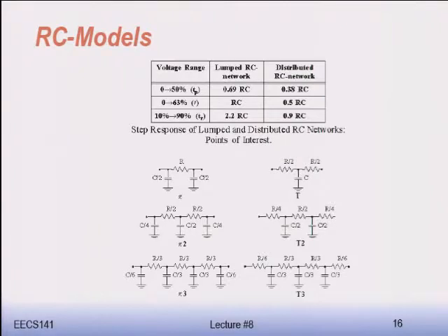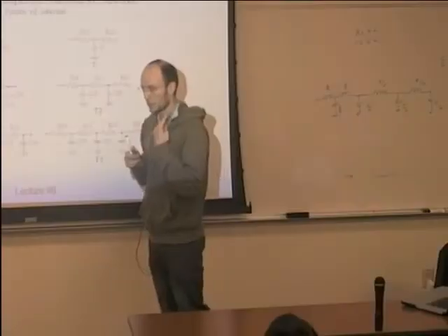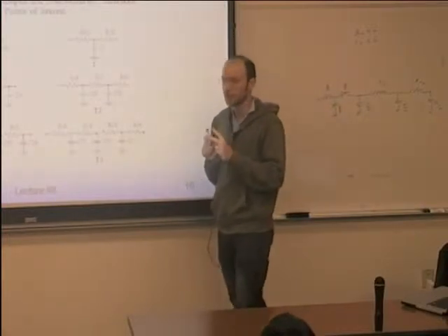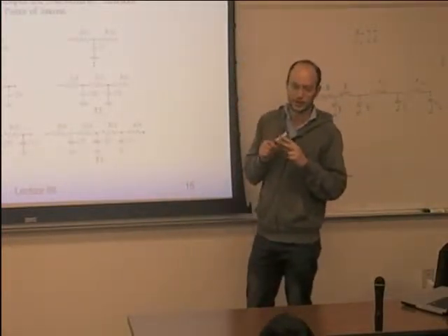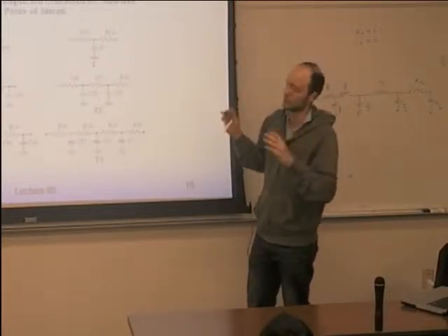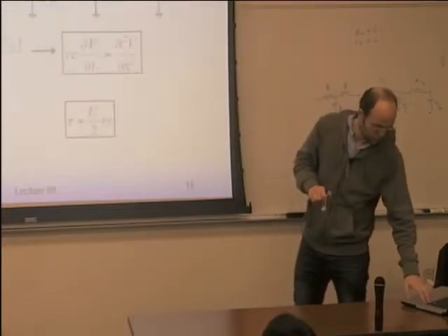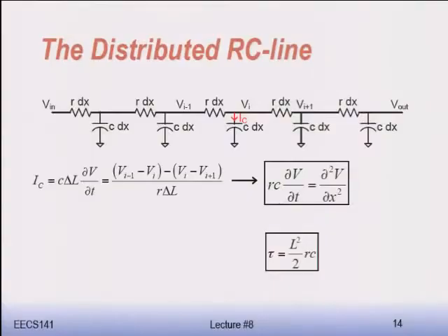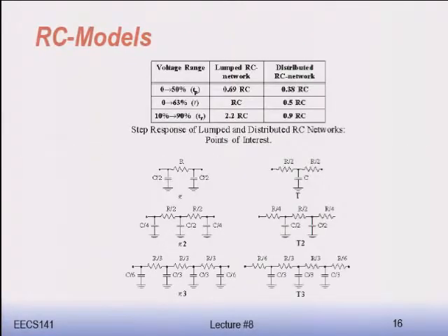It's probably okay. So now let's say that you have this long wire in your SPICE simulation and you want to include it. How would you do that? There are 2 ways. One way is that some simulators or tools have a wire model that is distributed, and internally the simulator does some approximation to this differential equation. You just need to say what the resistance per unit length is, what the capacitance per unit length is, and what the length is. So you don't need to think very much. That is often available.